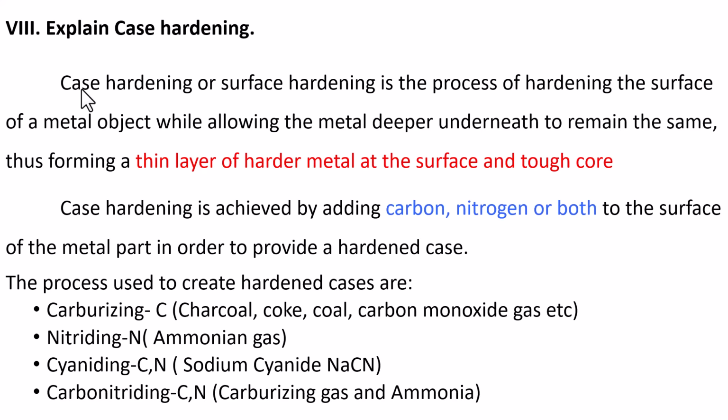such as resistance to abrasion, indentation, etc., when they are working. For example, a component working for many hours needs a hard surface to resist wear and tear. So we do the surface hardening. That means the outer surface is hard and the inner core is soft or tough to take the shock. Such an operation is called case hardening.